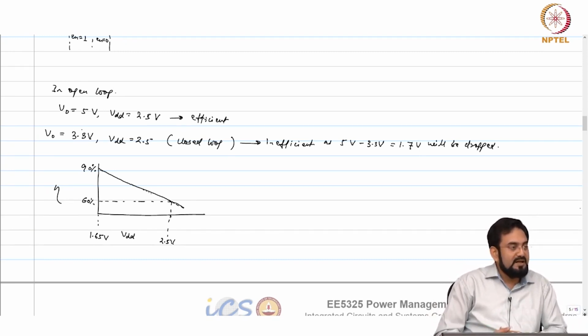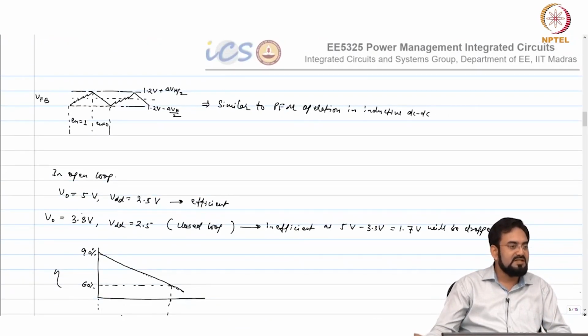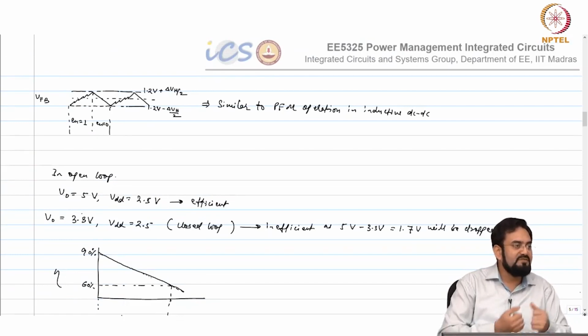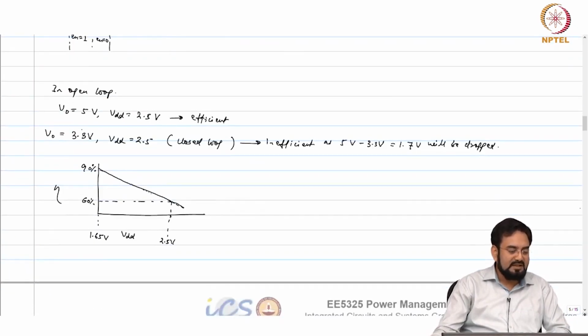I am always operating at 2x, but at 2.5 volt I need only 1.5x roughly. So, I will have a charge pump which has both a 2x setting and a 1.5x setting. When VDD is on the lower side, it operates in 2x mode, and on the higher side it operates in 1.5x.